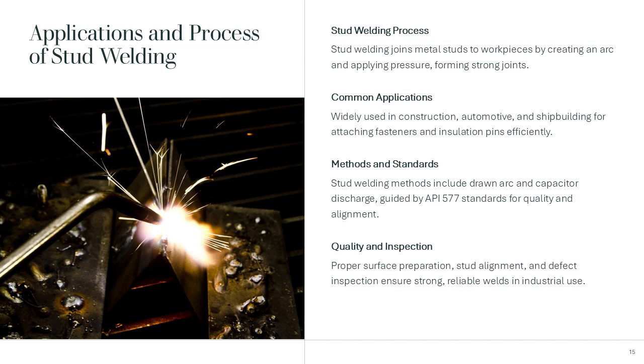Stud welding can be performed using drawn arc or capacitor discharge methods, depending on the application. API 577 guidelines highlight the importance of surface preparation, proper stud alignment, and inspection for defects such as incomplete fusion or misalignment. This process enhances productivity and structural integrity in various industrial applications.